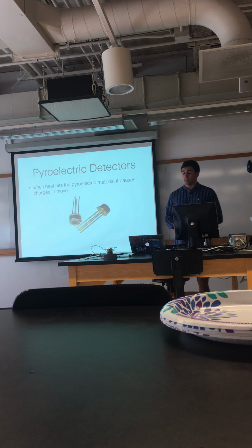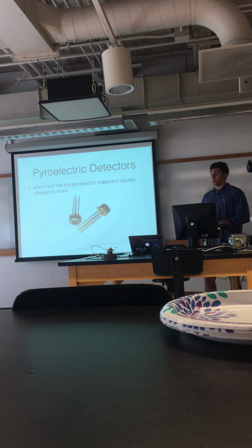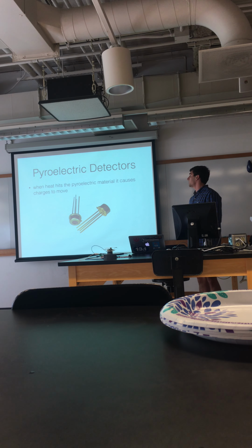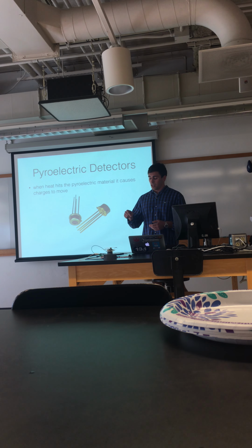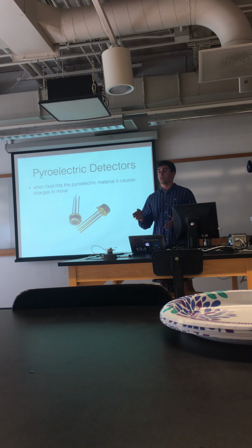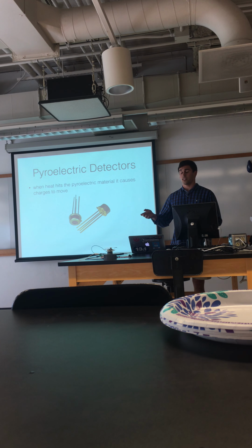So how I went through with this project was using pyroelectric detectors. I'm just going to call them PIR, and that's how I'll refer to them in the rest of the presentation. How they work is heat hits a pyroelectric material within the device, causing charges to move, and that is actually the signal that I'm going to read when I do the experiment.